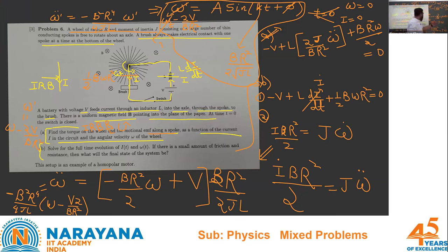So omega dot is also 0 at t is equal to 0 because omega dot depends upon current and omega itself is 0. So put t is equal to 0 in d omega by dt. So there are two variables, that phi and that a will be eliminated and that will give you omega as function of time. Once omega comes, you will get your current as function of time and everything will fall in place.